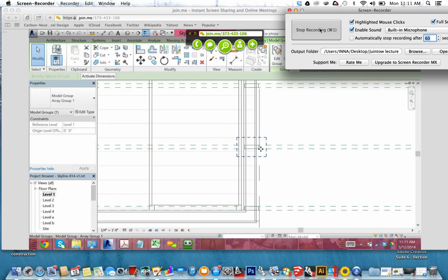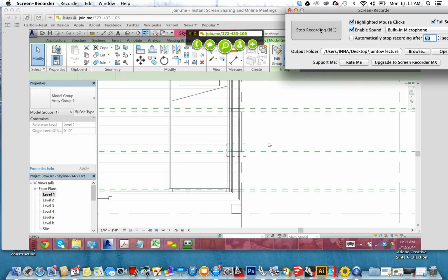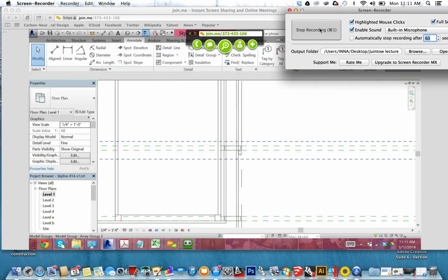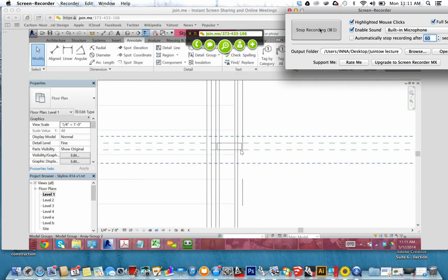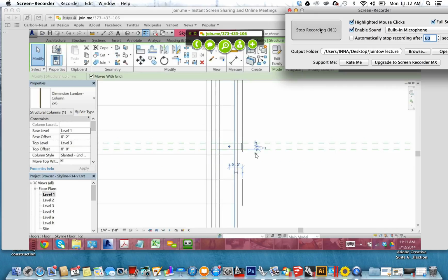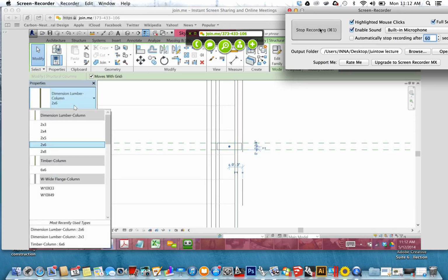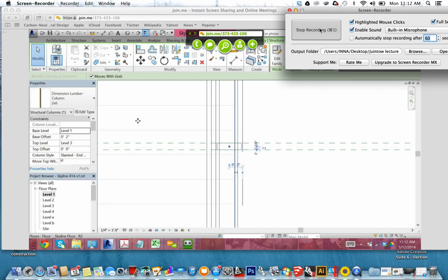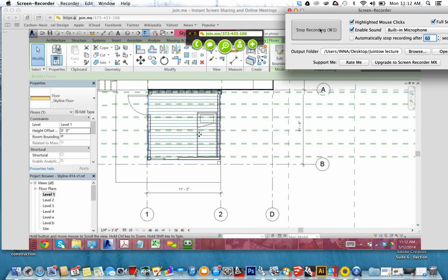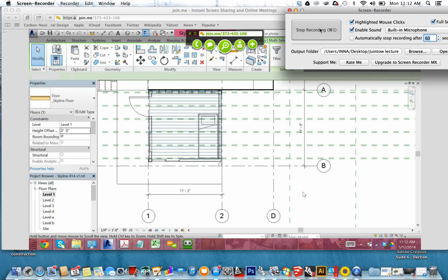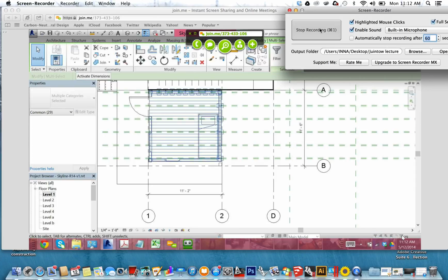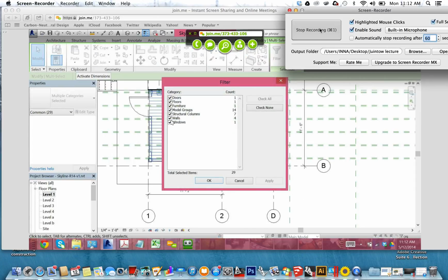So your things here are, let's ungroup them, okay? And let's change them to 2x4s. So dimensional lumber, oh, you did them as columns, I see, okay. So let's do some, this is a cool trick. Let's just go here and select everything. Then use this filter tool. This is like your next best friend, which is structural columns.